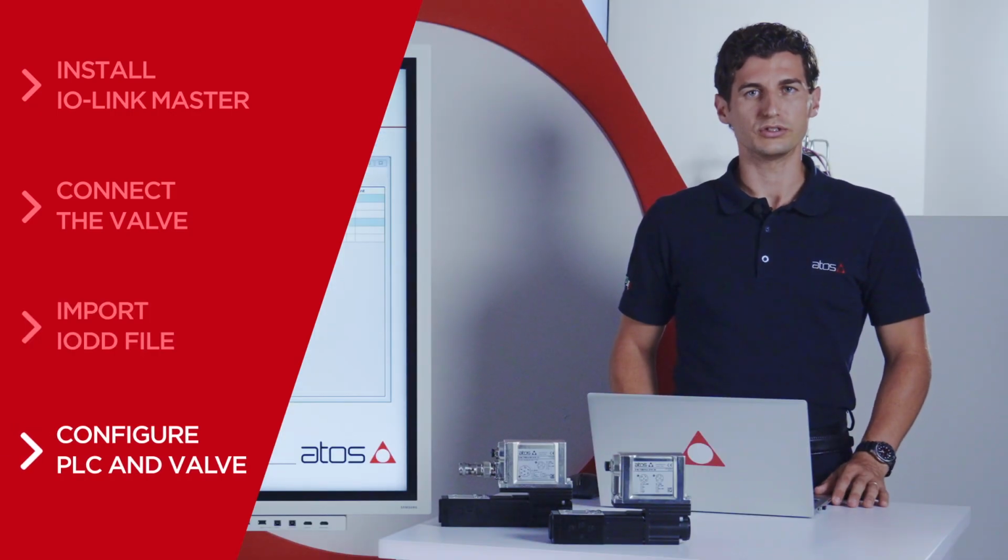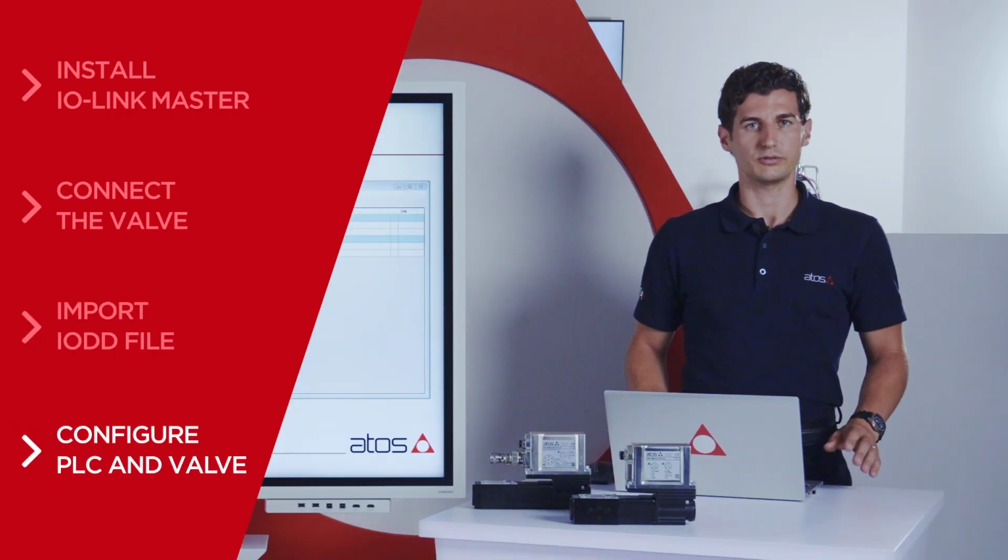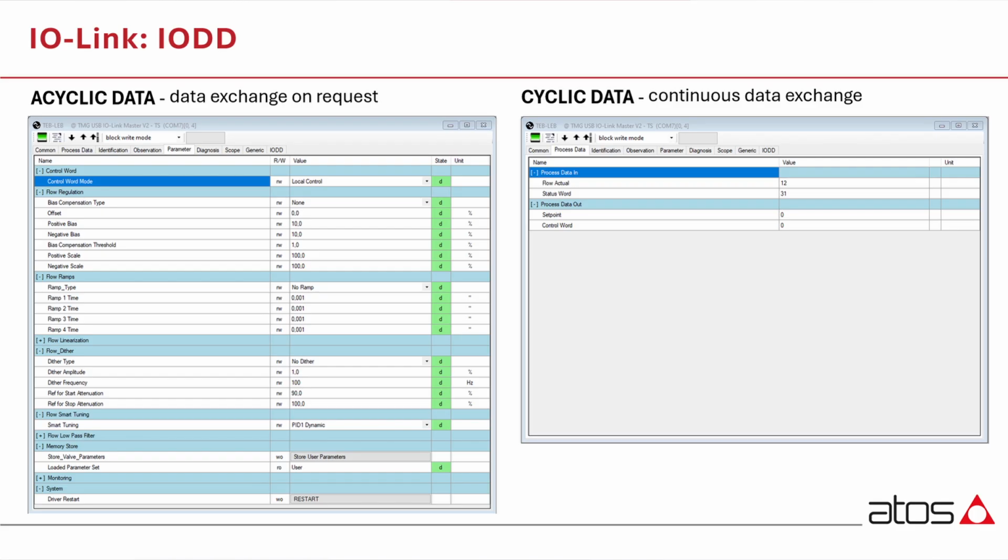Finally, you can configure the PLC and the valve, assign the correct port to the IO-Link devices, map the cyclic data, such as setpoint and control word, and configure acyclic parameters, such as ramps, gains, and limits. Now we have imported the IODD file using third-party software, but according to the PLC that you have, the visualization could vary. Once the IODD file is imported, you will see the list of valve parameters that can be modified.